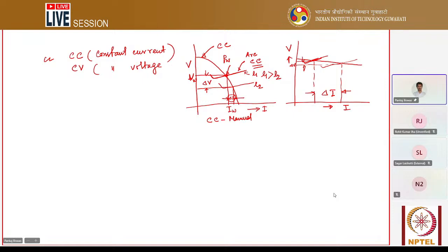So that's why constant voltage types of power source characteristic is generally used in automatic constant speed feed drive systems, feeding systems. What I am telling, understand? This you should keep in mind. So this is one way you can control the feeding. That means your deposition rate almost remains constant.